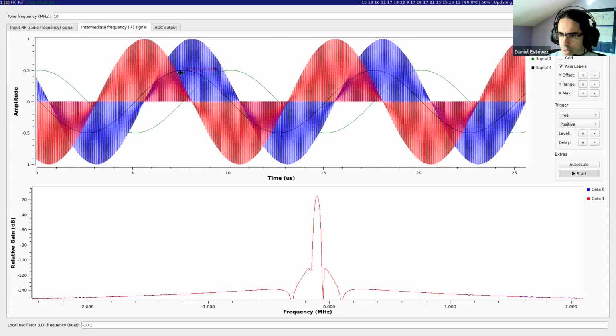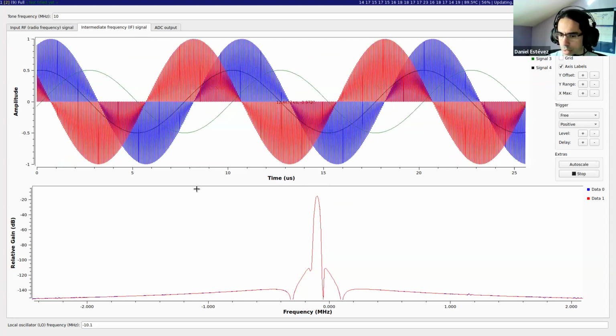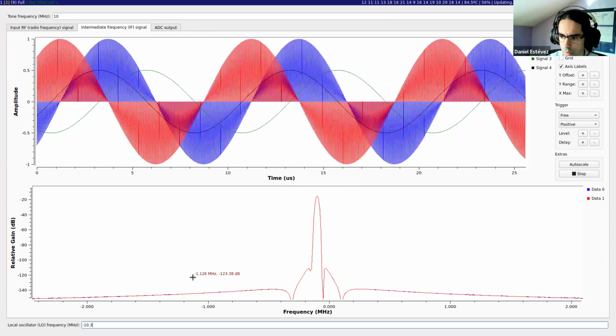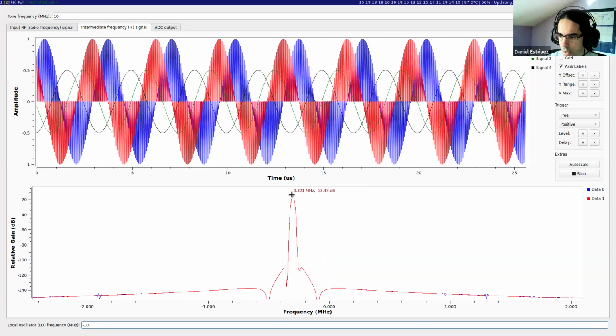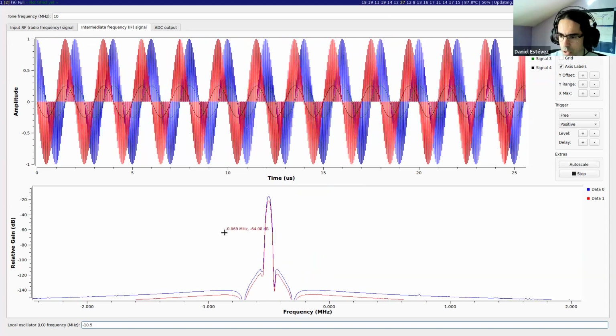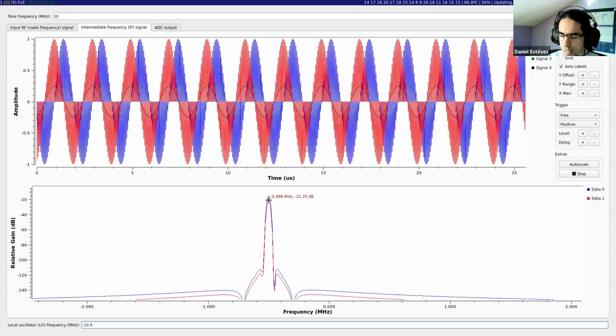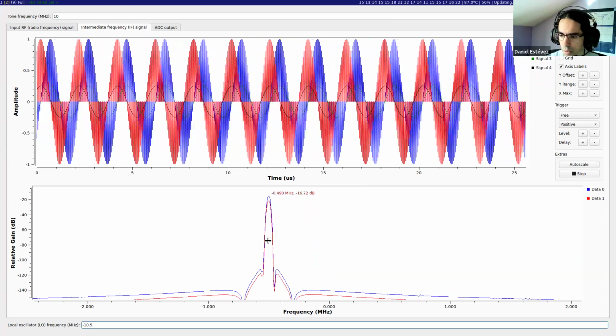As before, as in the complex multiplication example, this means that now the imaginary part, which is this black line, is before the real part, whereas for positive frequencies, it was the other way around. And we can also continue, and this is -10.3, so this is at 300 kilohertz, -10.5, and what we see is that the filter is symmetric in frequency.